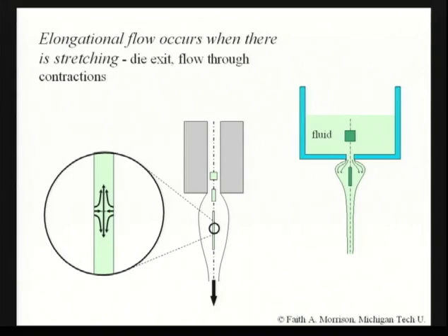So you can show, again, if you're very mathematical, you can show that all the deformations that a material undergoes in a complex three-dimensional flow can be split into these 2 flow classes: sliding and elongating. Okay? Simple shear flow and simple elongational flow. And so from a rigorous point of view, that makes these 2 choices very, very attractive, because as long as we can get the right combination, we're capturing all the types of behavior that the fluid might have.